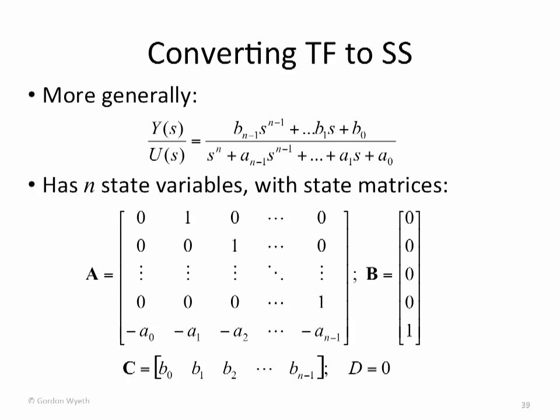But we're going to approach it in a slightly different way. So here is our continuous time system up the top, and I'm going to do a Laplace transform of it. So where we have x dot, we replace that with s times X, because s is the Laplace transform of the derivative. And we change all the little x's to capital X's. And now we have a Laplace transform of our state space system.